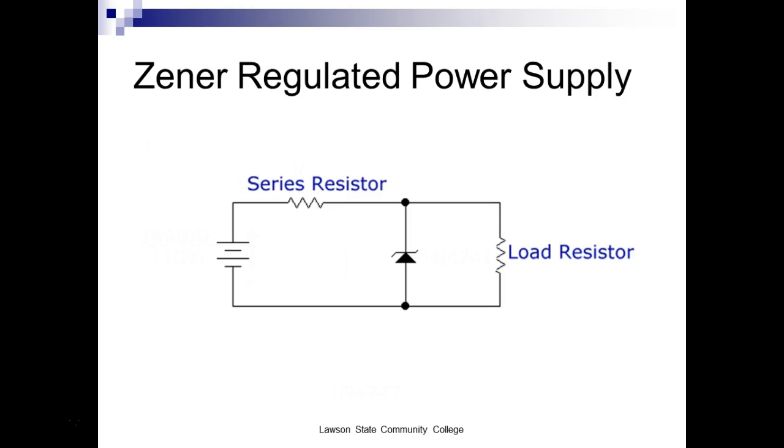First of all, I'm going to look up two things in my data sheet. What am I going to look up for my Zener? VZ. Well, we know wattage is 1, right? Okay. We're looking up a 1N4747. What's the VZ? All these are 1 watt Zeners. 20 volts, right? What's IZK? We need IZK because we're going to use that to calculate the resistance. Microamp.